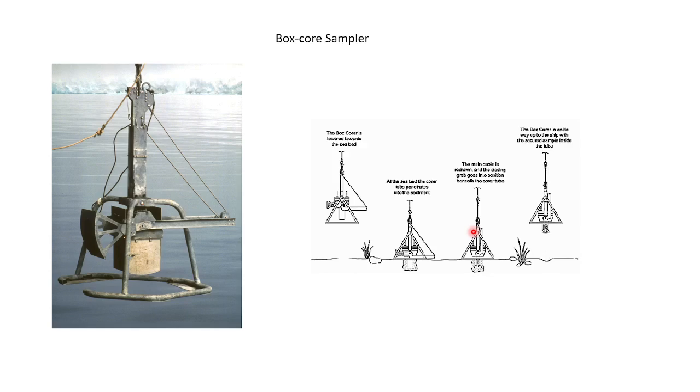So, the grab sampler that we have seen and the box core sampler that we are seeing, what difference do you find, like what kind of samples we'll get? In which one will the disturbance be less? Yes, in the box core sampler, it will be less disturbed than the grab sampler. And it can be used for the determination of density, moisture content, as well as the strength of the soil in the lab, because it will be less disturbed than that of the grab sampler.